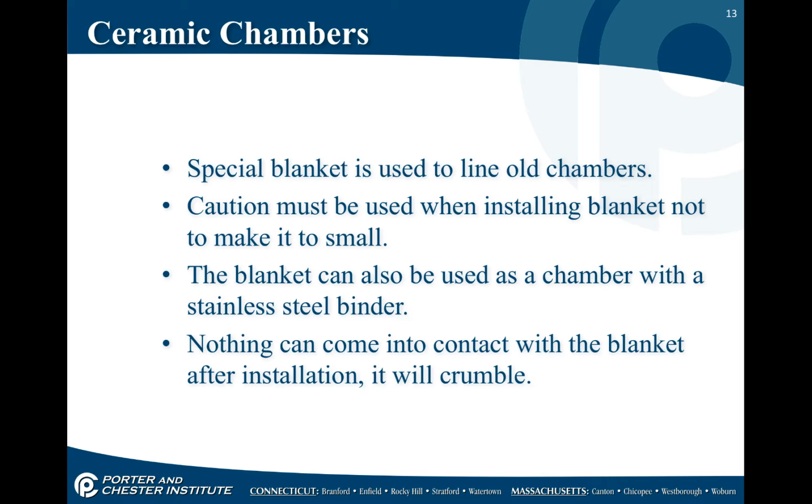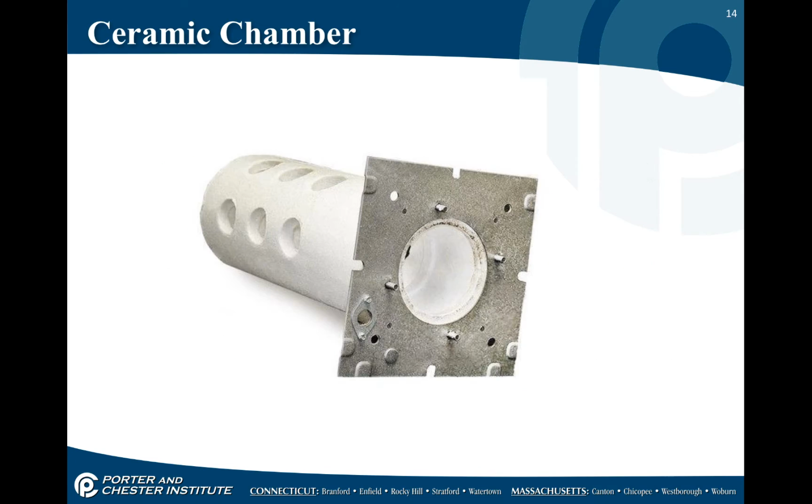The way the blanket is shipped to you, it comes in a plastic bag. It's moist, and it comes with a bottle of epoxy normally. What you do is you set this blanket up into shape, you put the epoxy on it, and then you fire the burner for like 10 or 15 minutes, and that will harden the entire thing and make it into one solid piece.